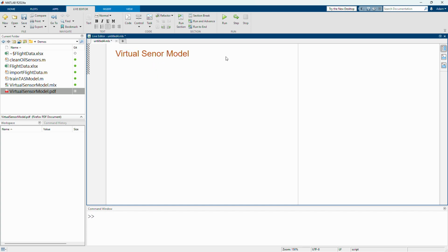And we can add some comments for what we are going to do at the start of this script. Let's say I'm going to start by importing some Excel data. So I can add however many comments that I want here to explain what's going on. But we can add more than just text. We can add outside images and equations and hyperlinks and tables of content. Let's say this is good enough for the moment. And then we can interleave with these more human-readable comments and text MATLAB code in these shaded regions.